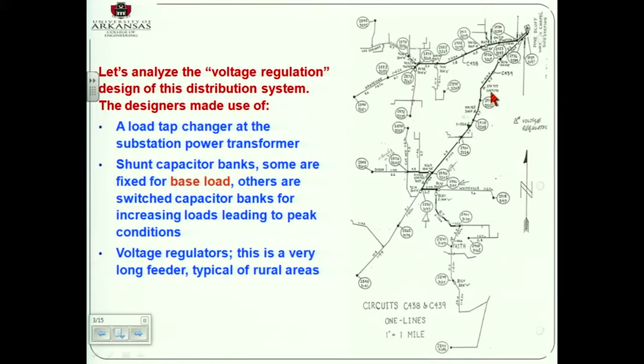And now here, right, is 600 kVAR, T and T. Basically, the control operates on time, but they also have a temperature override. Because now it operates on time and temperature override, because what are the loads that you're going to expect here?